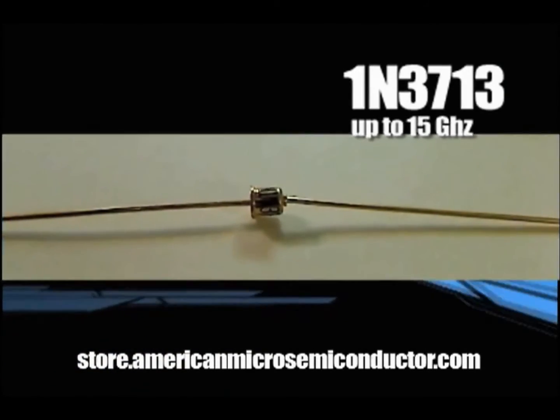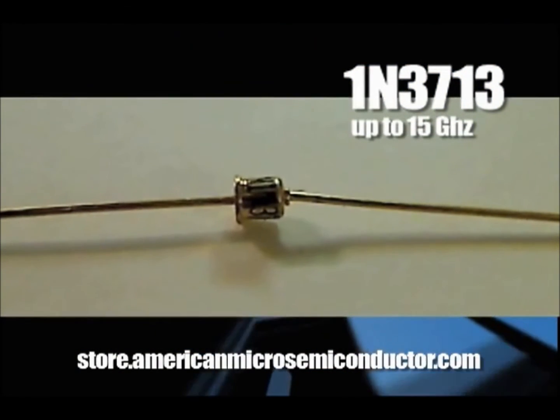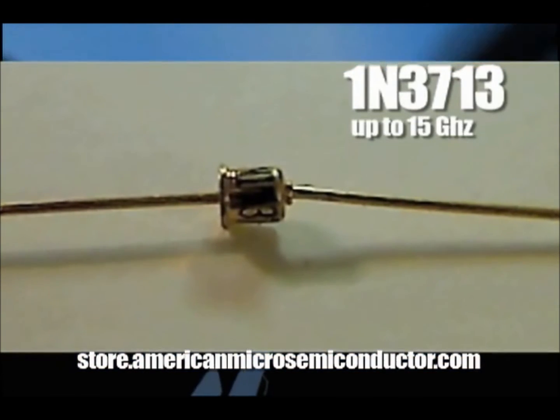Today's discussion is on tunnel diodes. A tunnel diode is a semiconductor device, a diode, with a negative resistance region. It's the negative resistance region that allows for very fast switching speeds. Typical speeds can be in excess of 15 gigahertz.